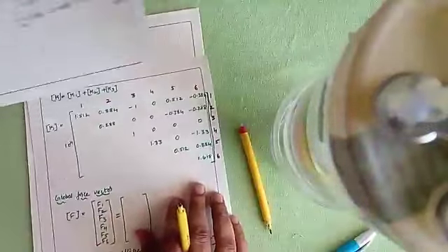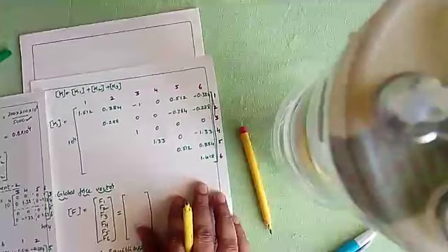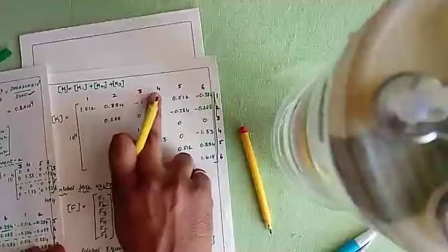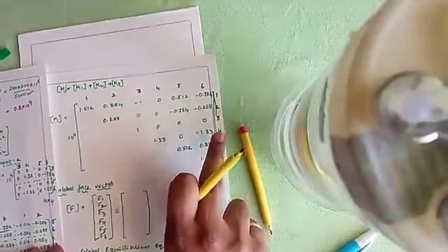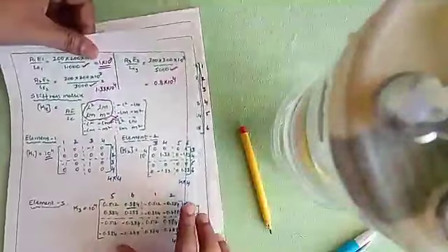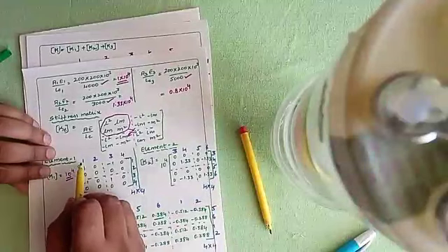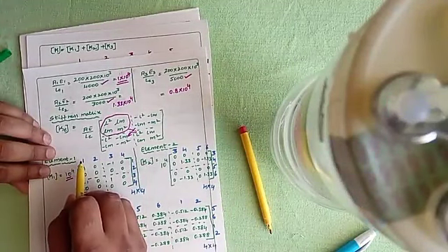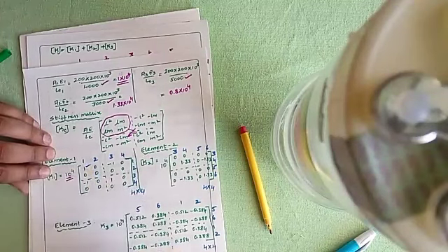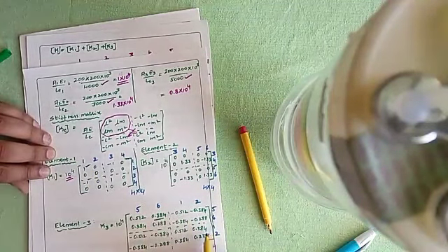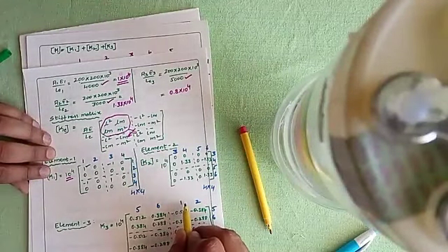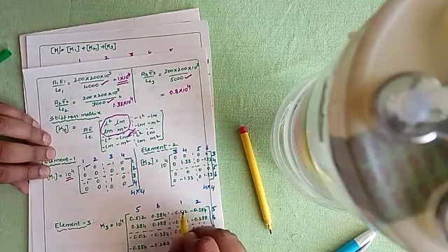This global stiffness matrix will be formed as follows. Write all the degrees of freedom, that is 1, 2, 3, 4, 5, 6, Q1, Q2, Q3, Q4, Q5, Q6. Now look at this one. How are you going to form this? In spite of degrees of freedom, you can read this as first column, first row. What is the first element? You have 1. Meanwhile, search your stiffness matrices: is there any stiffness value which is going to sit in position 1 and 1? Yes, there is one more value.